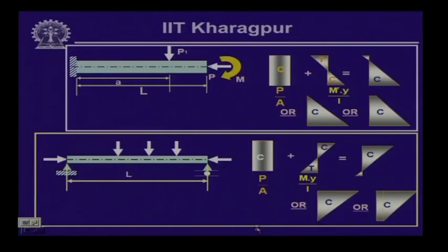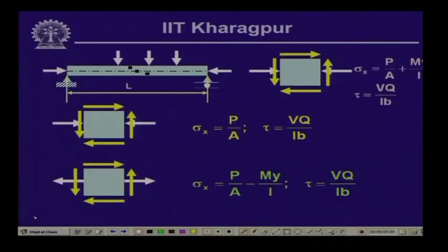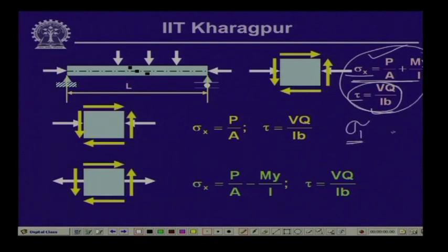Now, using this, if we would like to calculate the resulting stress, which we call the maximum value of the tensile or compressive stress, which is the principal stress maximum or minimum value, we compute it from the Mohr circle, and this is what has been done over here. This is for the normal stress and this is for the shearing stress, and based on this normal stress and shear stress we can compute the value of the maximum principal stress sigma 1 or the minimum stress sigma 2, these are the principal stresses, and also we can compute the value of the in-plane shear stresses, that is, the maximum value of the shearing stress that will occur at any point.